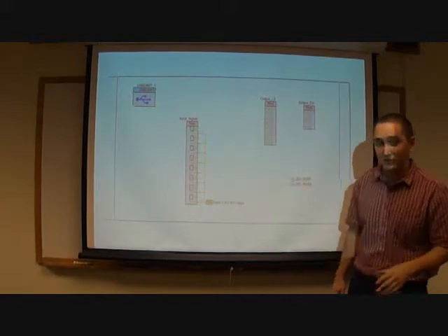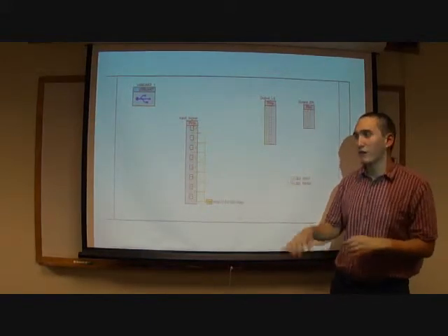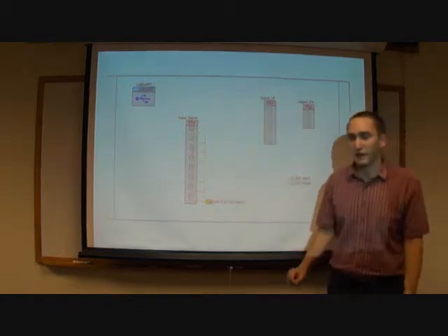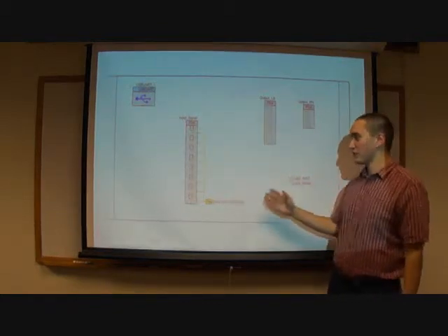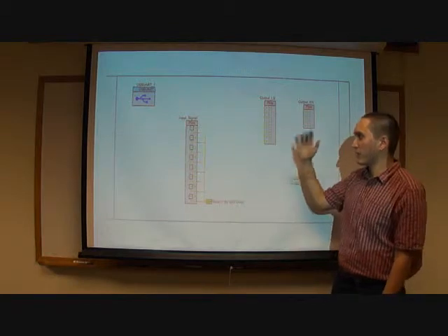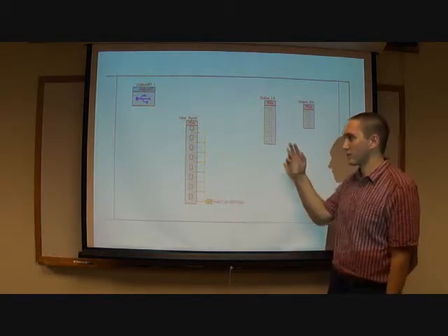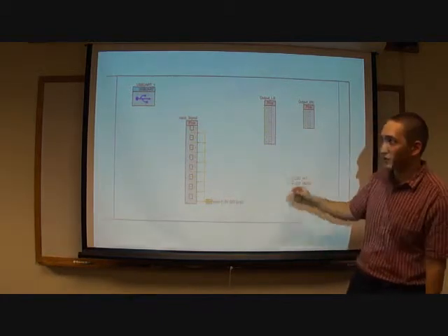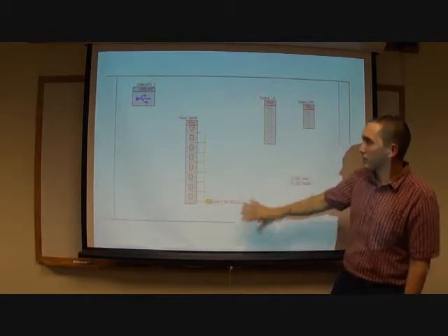Alright, now I'm going to delve into the firmware part of our top level block diagram. This is a screenshot from the PSOC 5 Creator from Cypress. It lets you design and implement all the internal circuitry and how things relate to each other. Actually there's no internal circuitry, we just have output circuitry: our output pins, our input pins, and our USB UART.